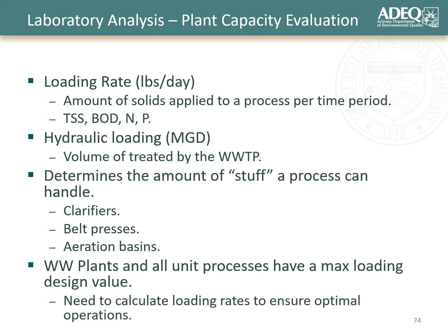And so if you exceed that amount of loading, then your clarifiers, your aeration basins may be overloaded with the amount of stuff they're designed to handle and will not perform as needed. One of the primary examples I like to think about is if you get too much BOD loading to your facility, that can overload your aeration basins and your blowers cannot keep up with the amount of oxygen that is needed to be consumed as part of that. And so as a result, the DO in your aeration basins will drop and you may get incomplete treatment as a result of that.